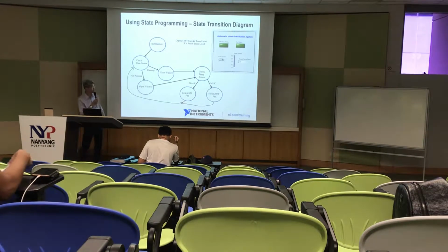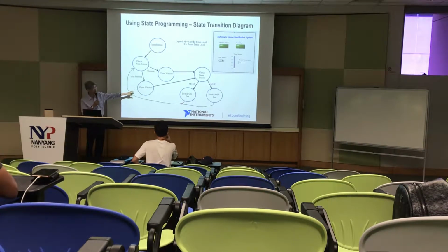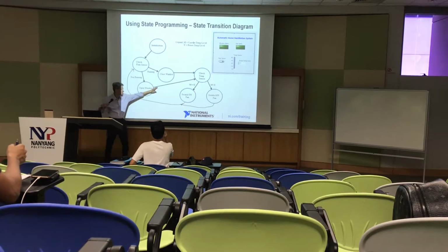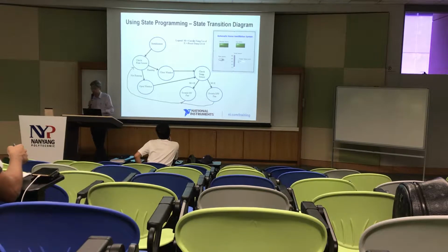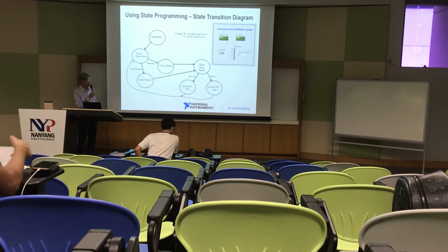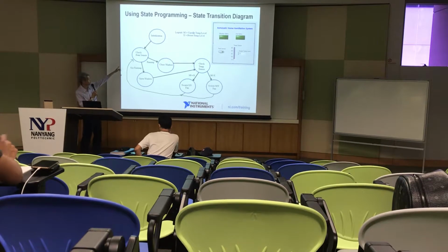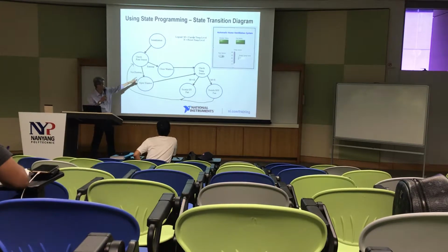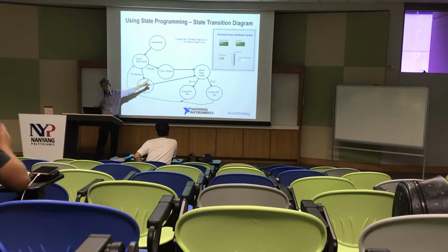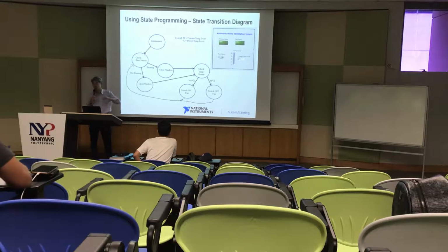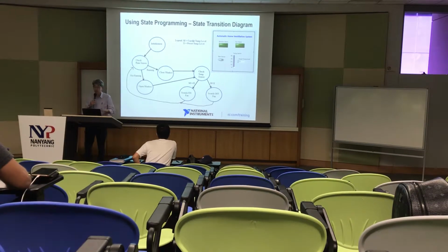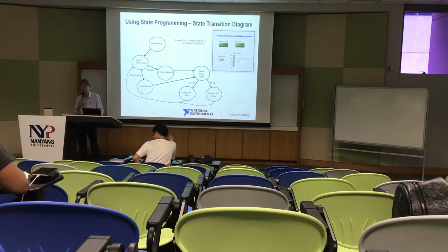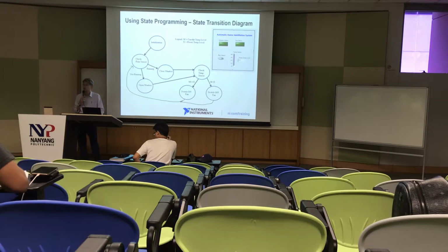So you notice also that some states going to the next state have only one arrow coming out from them. Therefore, for these kinds of states, you don't need a condition because there's only one way. But there are certain states, like for example, check rain sensor. After doing that state, he needs to branch off into 2 possible transitions. When there's more than one possible road to go, you must tell the fella to take the left or the right under a certain condition. You can't say, up to you.